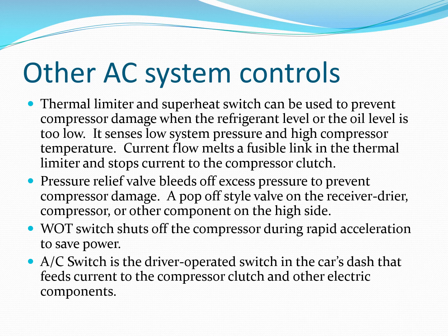An AC switch is really just a driver operated switch in the car's dash that feeds current to the compressor clutch. This might have a snowflake icon on it, it might say AC, or it may just be a little blue light that comes on when you push it. A lot of companies have put a separate switch on the dashboard that you have to push to engage the compressor. That's the AC switch. I have repaired a lot of air conditioners by simply instructing the customer how to push the little snowflake button on the dashboard.